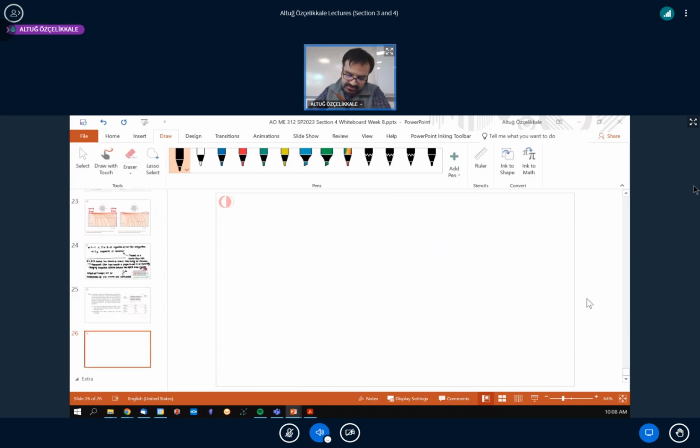So I'm going to go ahead and lay out how you solve a typical heat exchanger problem. You would first start by writing out the fluid properties and whatever is known associated with the fluid. Hot fluid mass flow rate is the mass flow rate of oil. That's going to be 0.1 kilogram per second. The specific heat of the hot fluid is the specific heat of the oil given in the table. That's 1900 joule per kilogram Kelvin.